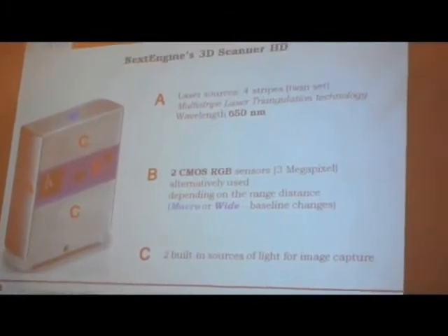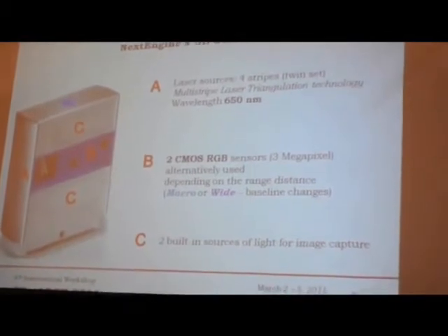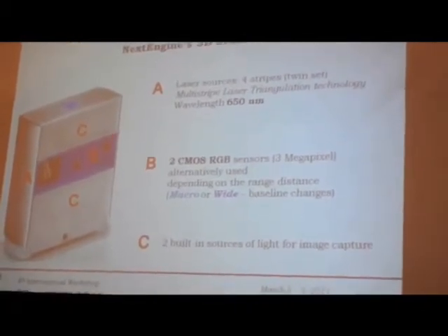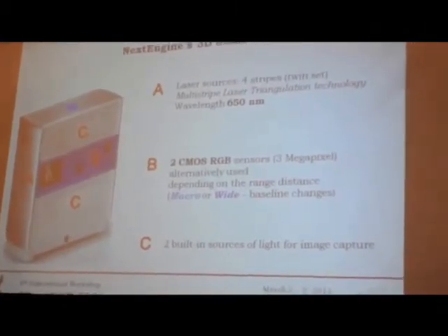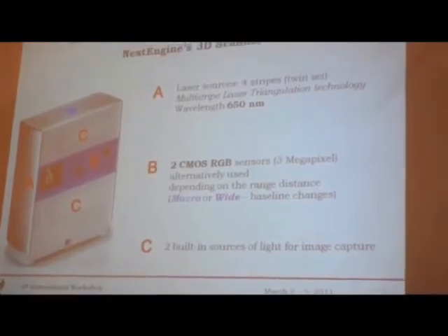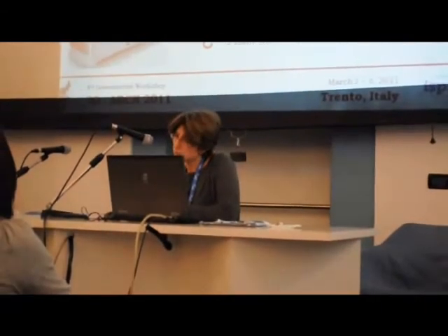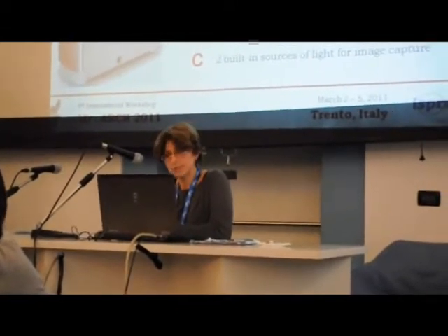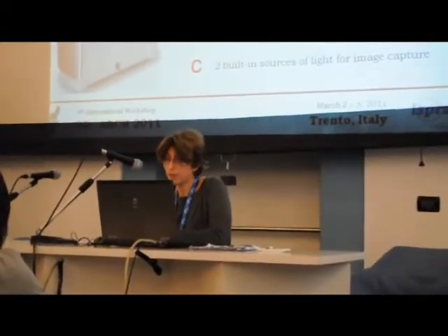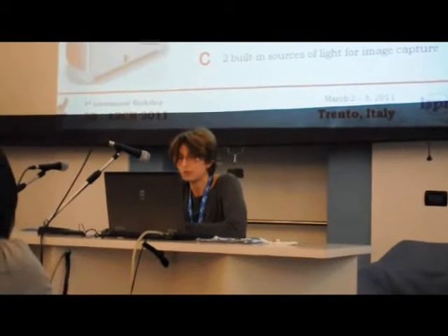This is the scanning device we used, NextEngine's desktop scanner. It falls into the triangulation-based family of laser scanners. It integrates measurements derived by 4 laser strikes swept across the surface of the object, which turns on a rotating base on predefined steps. And NextEngine captures photographic information of the same fixed views. The instrument uses texture for a very precise geometric correlation. After tests, we decided that the quality of this photographic information, even if not very high, could suit well the final targets of our project.